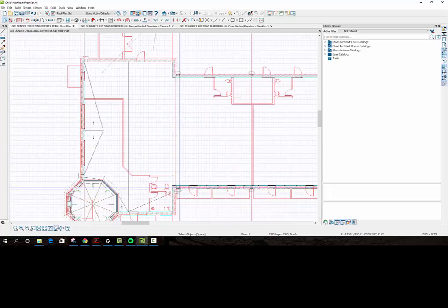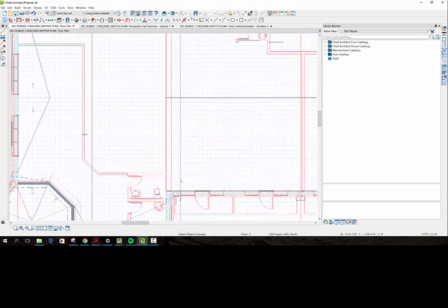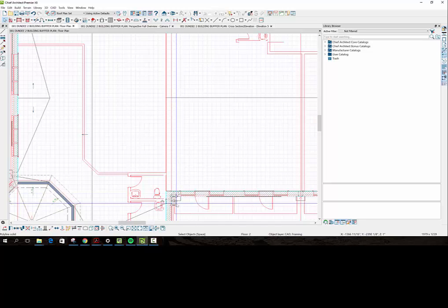Or you might want to do this double scupper box, which would be better than trying to get around, because this is the low point there. It's got to get around here. We're going to bid that up there. It's not a good thing. We're going to have a double scupper on that corner too. So let's do it. Control C.